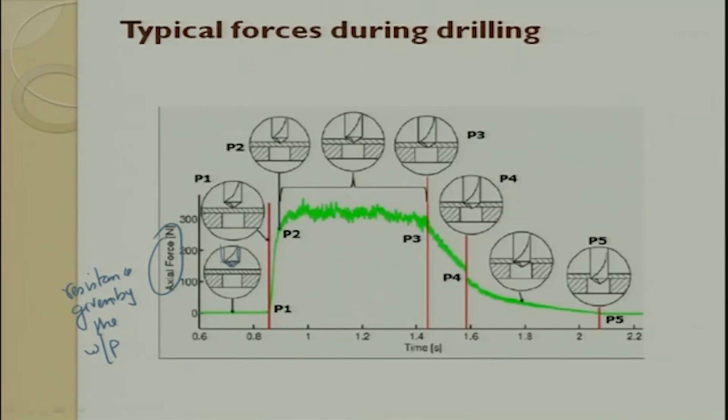You can see here this is the time. That means the drill is rotating and moving down, so you have given a feed rate. It touches, and the moment it goes to P2, the conical portion comes in contact with the workpiece.